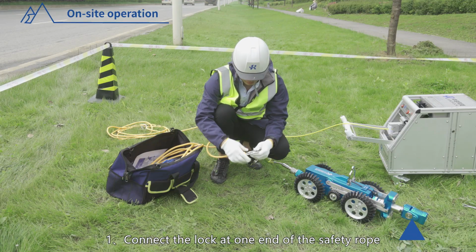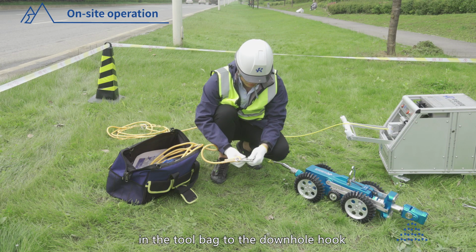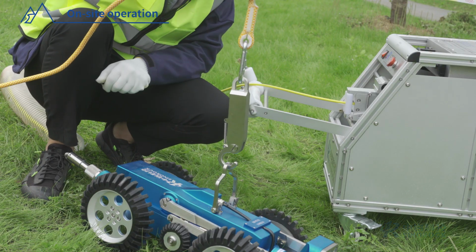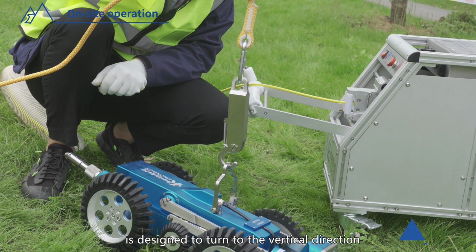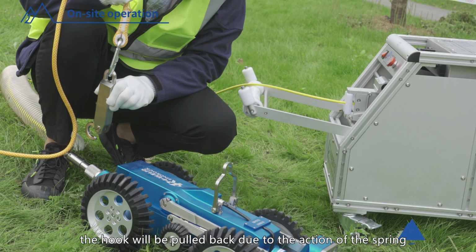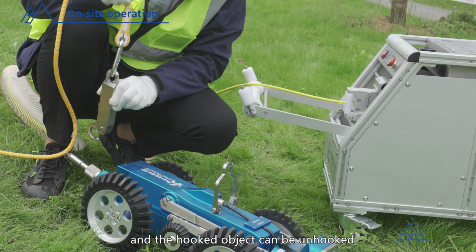4. On-site operation. 1. Connect the lock at one end of the safety rope in the tool bag to the downhole hook and hook the crawler hook with the hook. The downhole hook is designed to turn to the vertical direction to hook the object when the force is applied. When the force is released, the hook will be pulled back due to the action of the spring, and the hooked object can be unhooked.